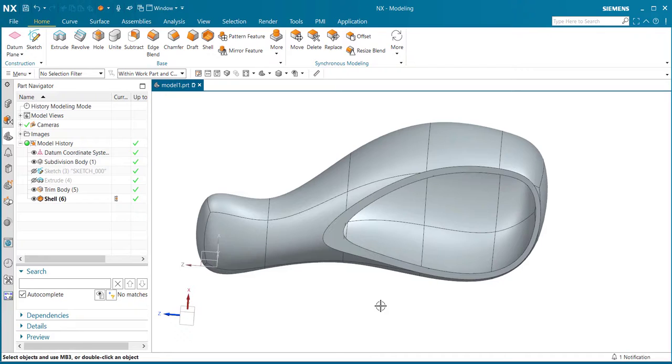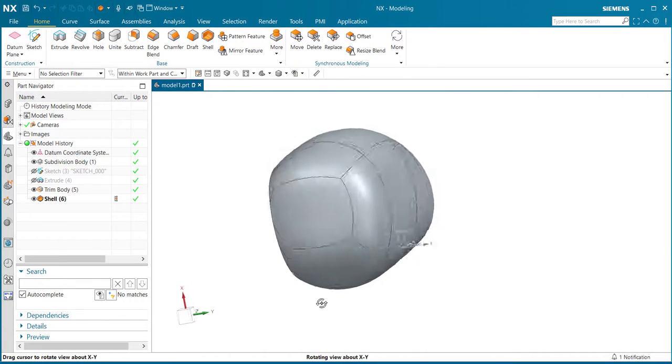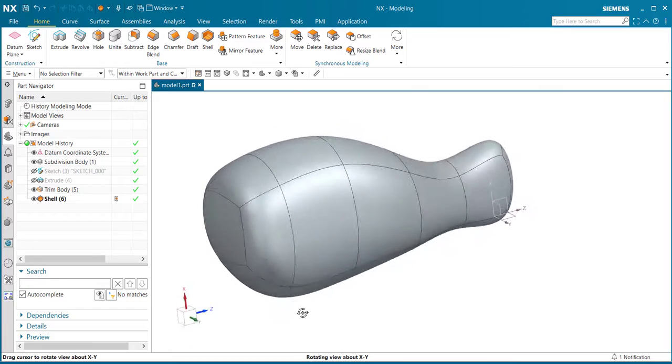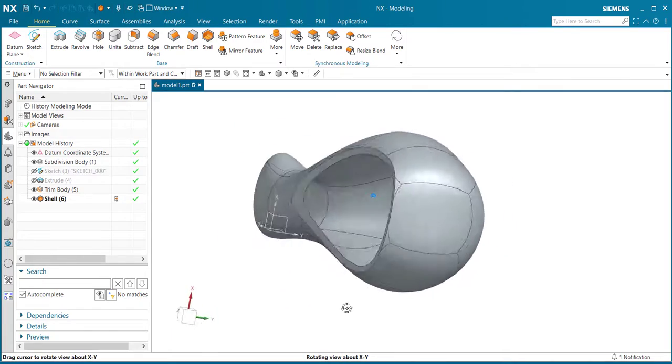The other thing to remember is when you create anything within realized shape, you want to use the least amount of surfaces or faces on your part. The more faces on the part, the more undulations or more little areas that can cause indentations or things like that. You want to keep your part pretty smooth, as you can see in the lighting here.